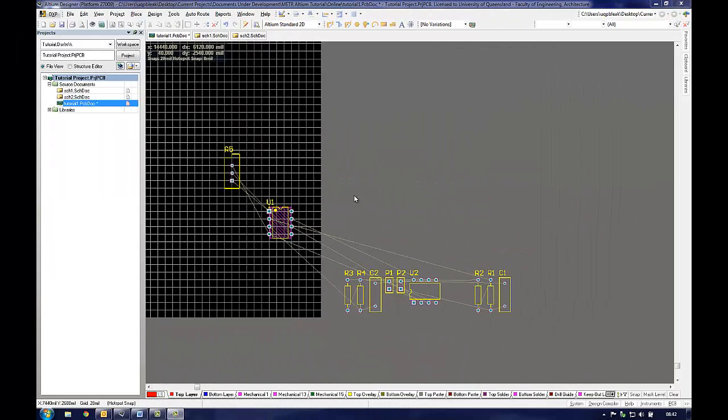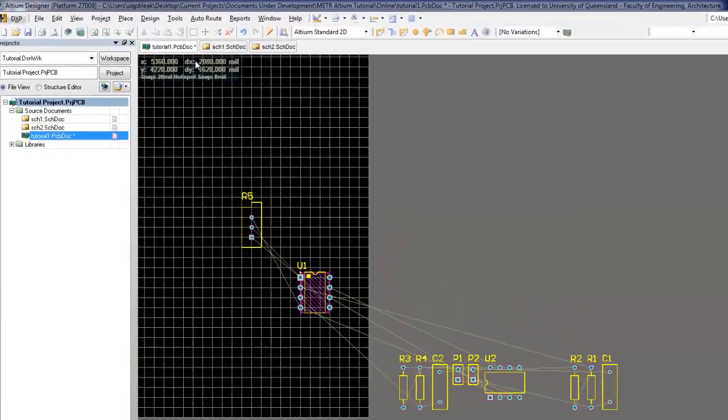The next step is to set up the design rules. This should be done before positioning any components or laying any tracks, as it assists the design process greatly. A separate document lists some of the general values for the design rules and explains how the rules affect the PCB. The design rules are accessed by selecting from the menu bar, Design, Rules.